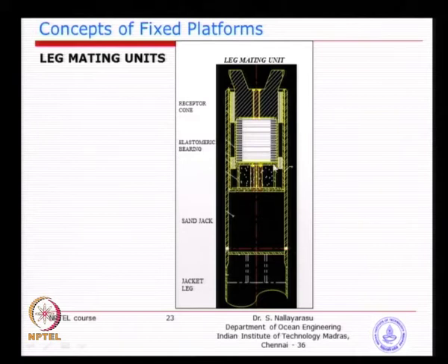On top of this plate you place several of the elastomeric pads, and on top of it you have a receptor cone, a metal piece prepared in such a shape that it will receive the load without bigger problem. So, basically when it is impacting there, the elastomeric pads will compress and the shock absorption will be taken by the sand in here. You are not seeing that dot color, but basically inside here is fully filled with sand.